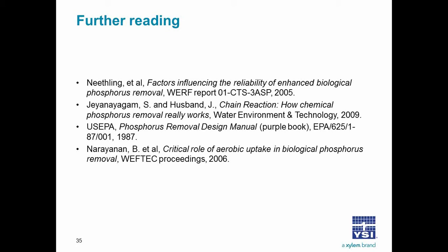But what I do have is there's a certain hydraulic retention time, so a straight calculation of hydraulic retention time of maybe 1 to 2 hours, and the total SRT for biological phosphorus removal is 7 to 12 days, and of course only a fraction of that is anaerobic solids retention time. So although number of cycles could be calculated, if my answer doesn't suffice, let us know, and we'll reply and follow up.